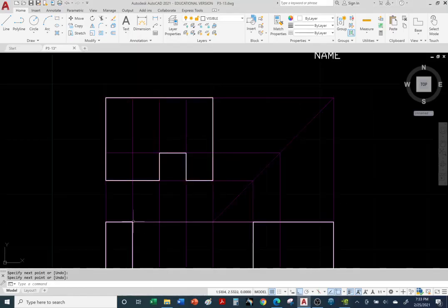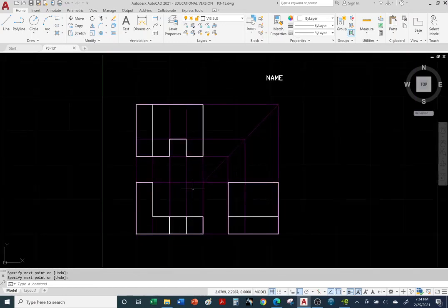Okay, so let's go back to AutoCAD. We're missing the line from this vertex here. We're going to draw a line. Now, since we used the line command last, if we're going to repeat the same command, you don't have to constantly be clicking on the line command. You can hit spacebar, and it remembers that line command was the last command. And let's go ahead and draw that line. And once you're done, you can hit escape or right click enter to exit. There it is. Okay, we're done with the top view.